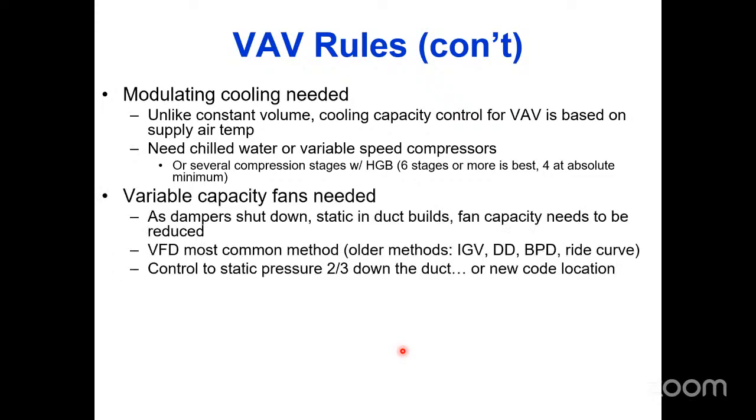I have to have variable capacity fans. I already mentioned that to you. We're going to do that with the VFD. That's the only way you're going to do it now. The pressure sensor is going to be mounted in the duct, and then the VFD is going to be controlled to maintain a specific static pressure. The way we've done that, okay, there's three ways.